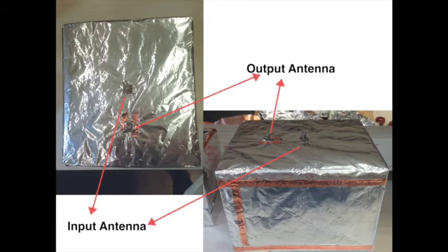So I built my cavity resonator. What I did is basically I had an insulator box, and I covered it with aluminum foil, which is a conductor. I covered it only with one layer, and I made sure that the sides were all smooth in order to make it like a real box, because not making it properly or leaving gaps in between might cause unwanted modes, which I don't want. And I put some copper tape on the sides to close the box completely.